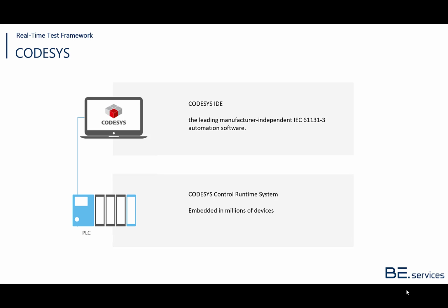The RTTF was developed to test and measure the performance of ICS that are based on the CODESYS technology. CODESYS is a soft PLC solution developed, maintained, and distributed by the company of the same name. While the technology was developed as an IEC 61131-3 programming environment, it's grown to a complete automation suite, providing I/O control but also motion control for single and multi-axis applications, as well as robotics. The IDE provides editors for HMI, field bus configuration, and add-on tools to ease the application development, i.e. debugging features, interface to subversion, profiler, or static analysis.